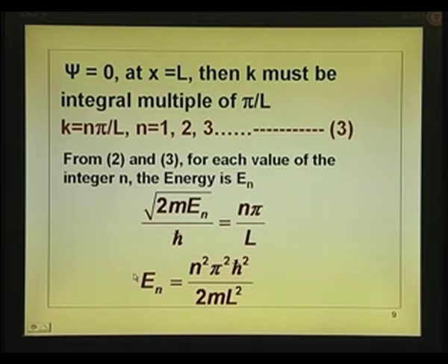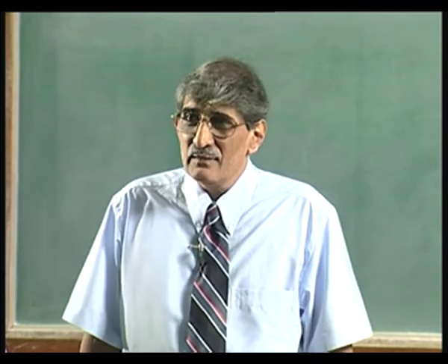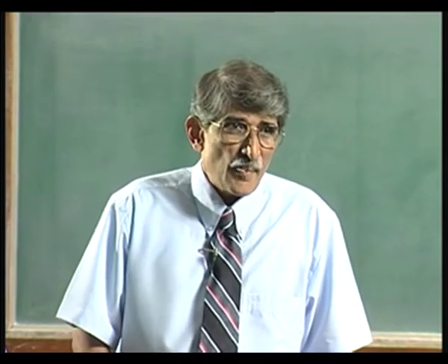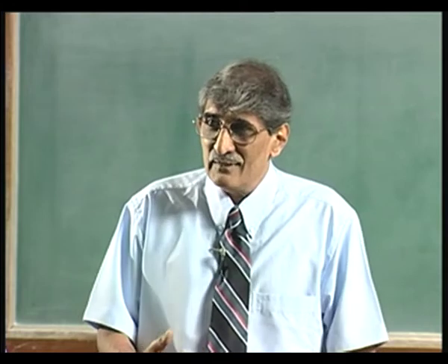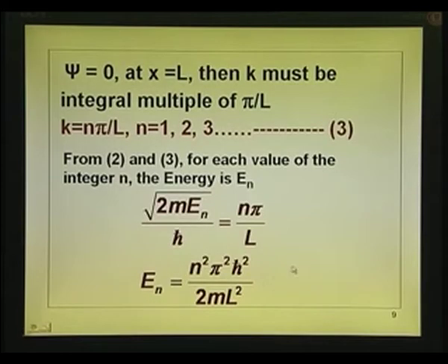If there is no quantum well, the energy level is continuous. So, that is why in a conduction band where there is no quantum well, the energy level is continuous. L is actually tending to infinity, so the energy difference tends to zero. Okay. Continuous energy levels are permitted there, but the moment you have, like in the case of a heterojunction, a potential varying like that, you have got a finite L.